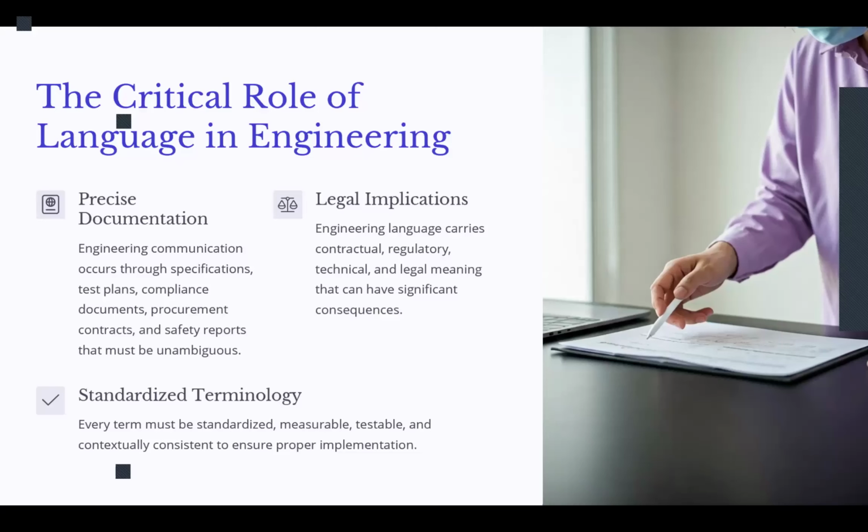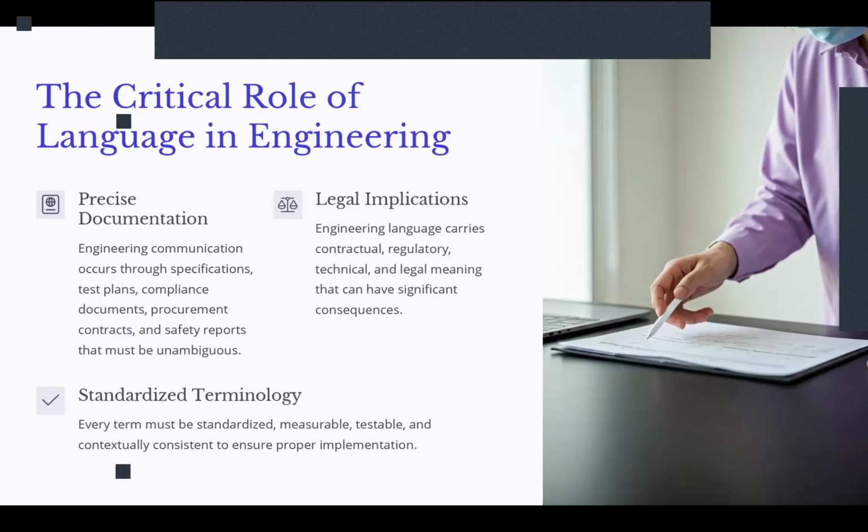See what a difference it makes. In one domain it is protection against safety hazards. In another domain it is the basis of the definition of low noise, so it's basically a reference signal. Now, what is chassis ground? Maybe you have heard about that. Chassis ground is basically a metallic bonding between the frames of any electronic equipment to prevent electromagnetic interference. So you see in three different domains, we have three very different meanings for one word. Ambiguity could destroy your design, any kind of brilliant idea that you have.